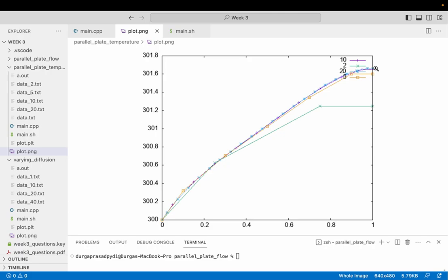Even that should be the case. As your flow speed increases, this curvature will shift. So your maximum temperature will be much higher somewhere in between. The difference between the maximum and minimum temperature will keep on increasing as your flow velocity increases. Anyways, yeah, I got it. You got it. Something to look at. I need to do some research.